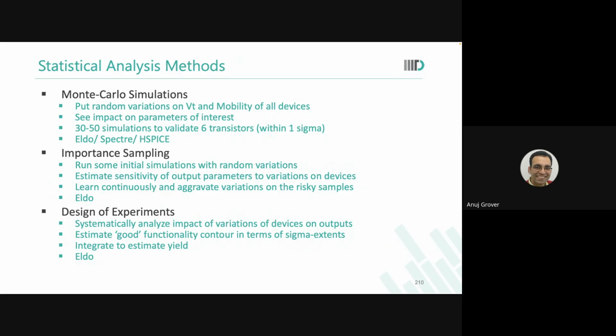Okay. Now, one thing that you need to realize is that Monte Carlo is a uniform distribution kind of a mechanism. What it does is, if it is told that this is a Gaussian distribution, it will uniformly distribute samples across that Gaussian distribution so that you get to see worst case results also in one of your simulations. Hopefully. It's always hopefully. There's no deterministic thing in it.